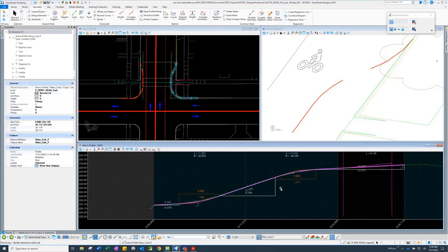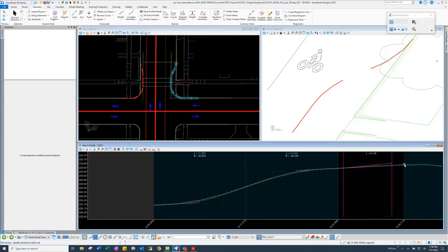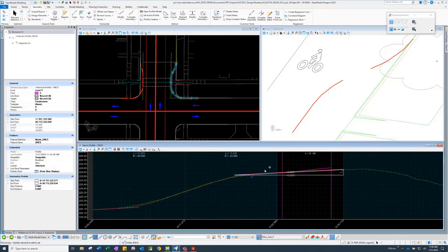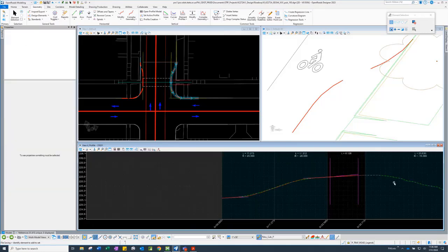So you did that with control lines instead of manipulating the geometry itself. Yeah. I found that this is less crashable. Profiles are touchy. This also allows you, if this was a point, the control lines would draw, you can draw them backwards. So this line could be drawn from here to here, and it doesn't cause continuity issues.